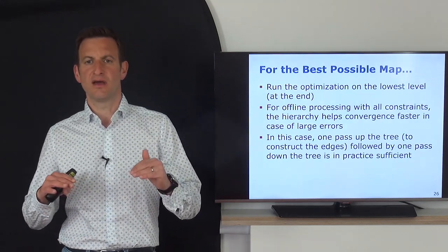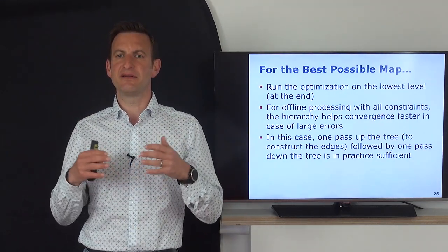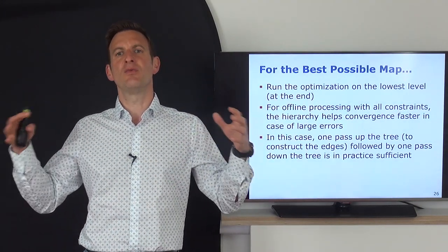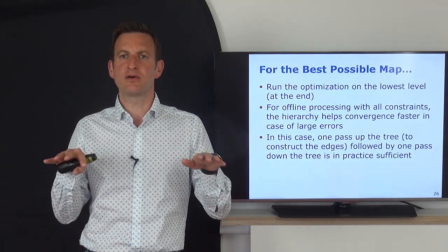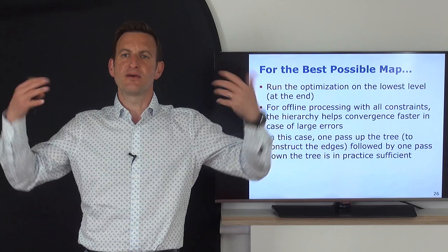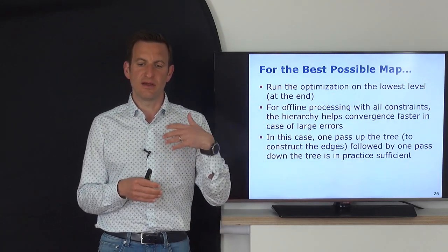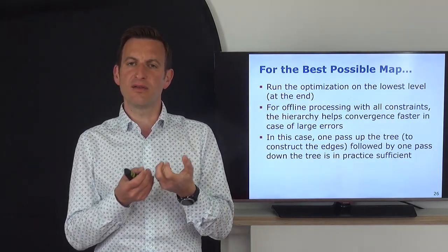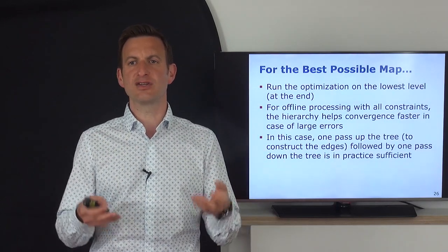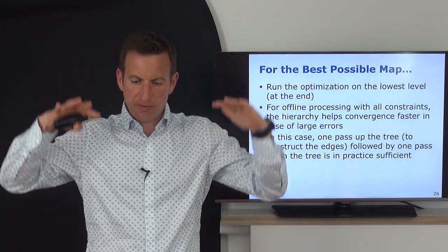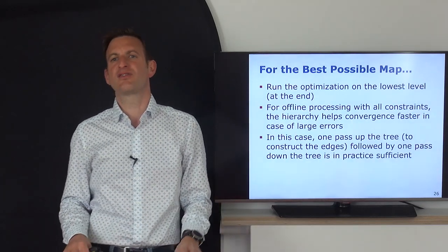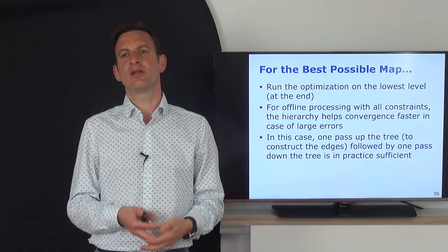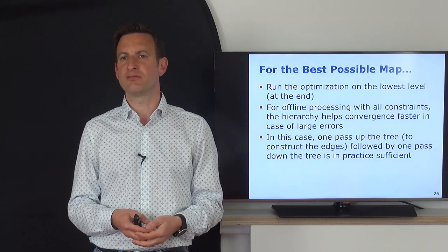The reason is that if you go up to a higher level, you have an approximation of the original pose graph, but an easier to optimize problem. And you're optimizing a smaller number of nodes and shifting all the other nodes in an approximate fashion in a similar way to those representatives that you're optimizing. And it typically has the effect that it is much, much faster to perform these operations, and all the nodes come closer to their final location more quickly. Then if you propagate this information downwards, you have a better initial guess for the optimization on the lower level, so that even if you're solving the original problem, you typically need a smaller number of iterations overall in order to optimize your maps on a lower level.